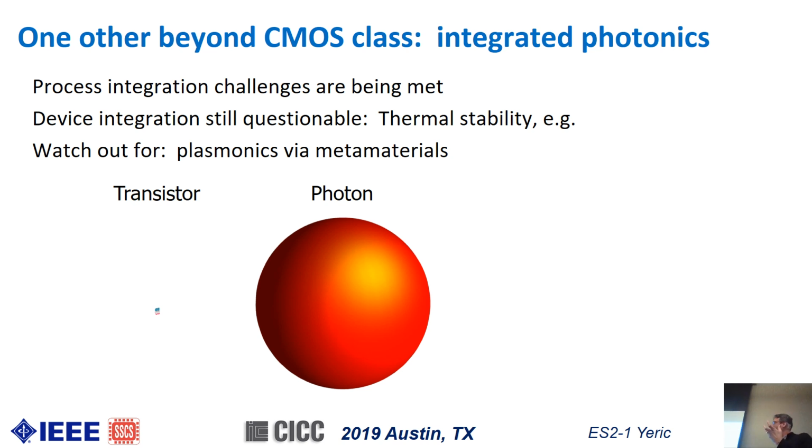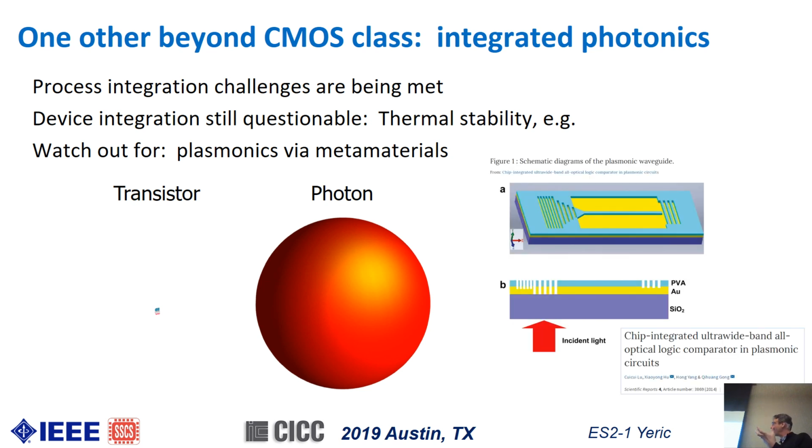It's a really interesting offshoot of the success we've had of Moore's Law, because what people have found is you can actually, using the ability to pattern nanometer features, layer-wise and feature-wise, convert this gigantic photon into what's called a surface plasmon that actually is really small, can propagate on nanometer wires, and then pop back out as a photon later once you're done with it. So it's really science fiction stuff. And so that's a field called plasmonics.